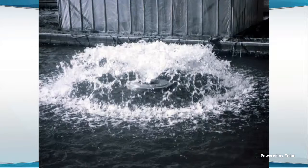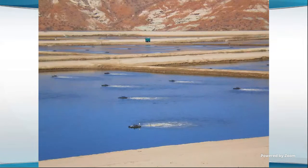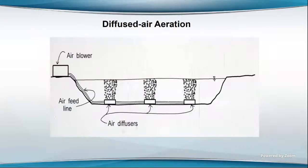Because you see, this aerator just pulls in the water around it. And pretty soon it gets a high oxygen concentration in the water all around that aerator. That reduces the efficiency of aeration as the concentration of oxygen in the water increases. But these aerators that push the water away from the aerator, see, they're always bringing in water behind them that has lower oxygen. So the efficiency of the aerator doesn't decline over time.